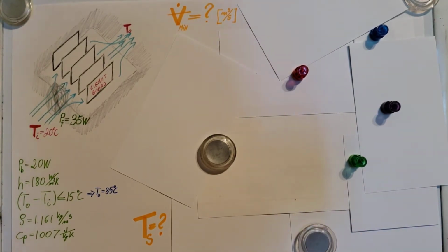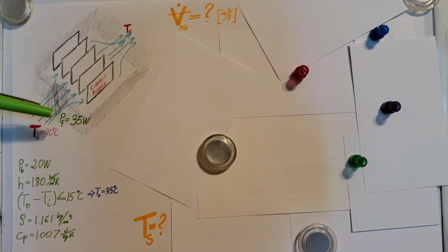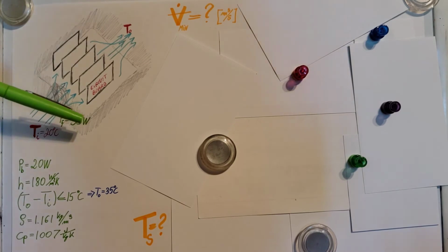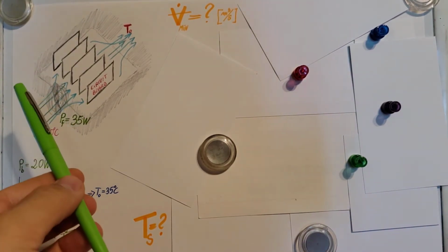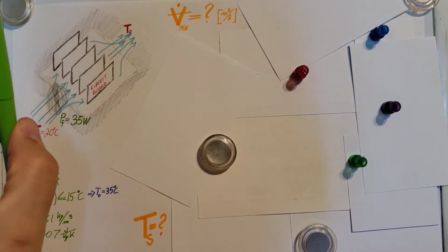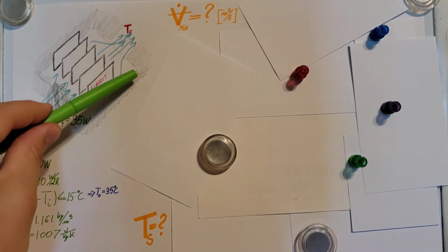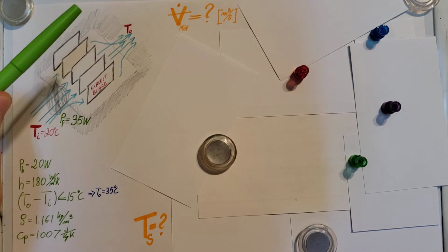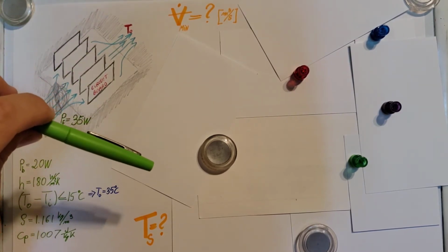Okay, so we're gonna use energy balance for solving this problem. And I'm gonna tell you right now what the energy balance is written onto. So what is our control volume, so to say. We're gonna be using this enclosed box, but our control volume is the air inside it. So from here all the way here, just the air, not the box. The fan is not included in our control volume.